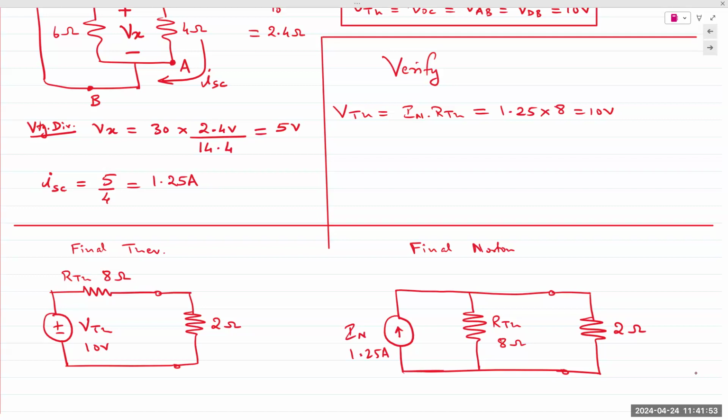Current source will always have a resistor in parallel, and a voltage source will always have a resistor in series. Because a current source will supply its rated current no matter what is connected to it. So if you're connecting a resistor in series with a current source, you cannot actually depict the real life resistance. I mean, real life current source.